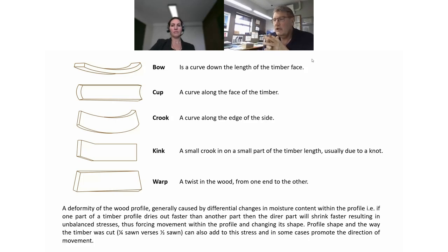And again, when you saw me talking about how I love quarter sawn, or I kept on saying quarter sawn is more stable than the half sawn, not being biased, I'm just saying it is what it is. Well, you're going to get a lot less cupping with a quarter sawn board than you will with a flat sawn board. It's just fact. So it's just interesting to know what you're looking at.